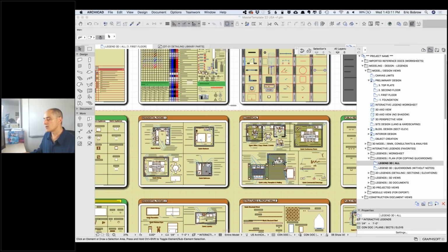And then when you're actually placing elevations or spot elevations, or you're setting things in terms of a mesh, you can choose whether you're referring to sea level elevations or you're referring to project level elevations. So in general, that's what we want to do, is have the project 0 be a convenient reference point, maybe on the ground floor, but have a defined relationship to your external datum point. Okay. All right.